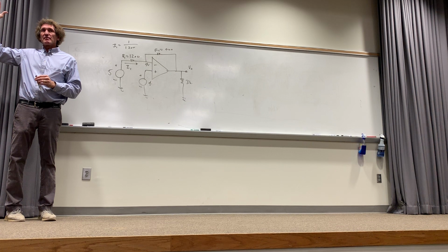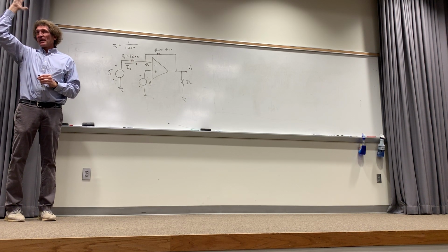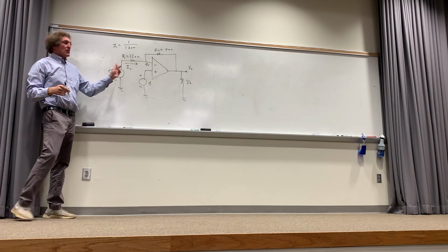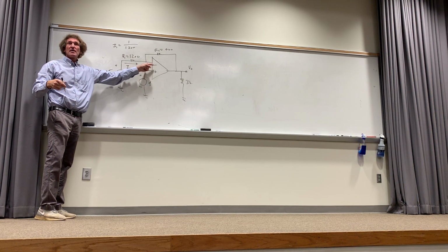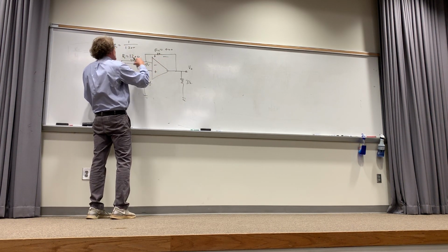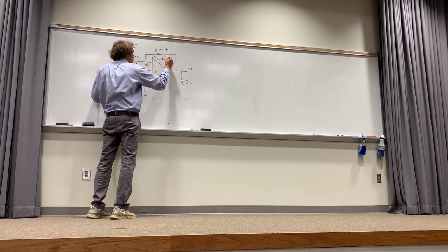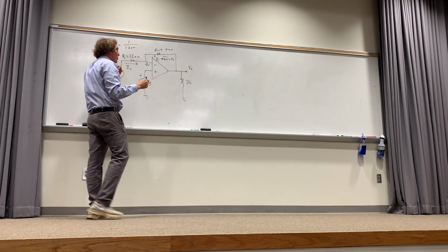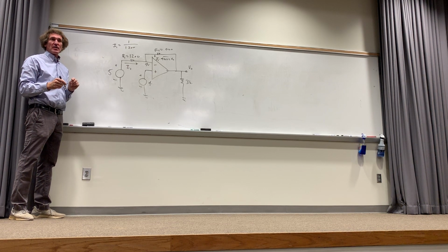Can you see it, Isabel? Back there? And far back, can you see it? Far back, down at the laptop. Can you see it back there? All right, I gotta make sure. All right, now that current, problem's done. How much of that current can flow through here into the negative? None. It all flows around here. That means this voltage is what? That voltage is I1 times 4200, call it V2, or it's 4200 times I1, or 4200 divided by 1200. 42 by 12, right?